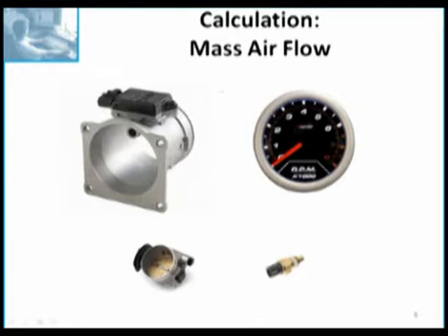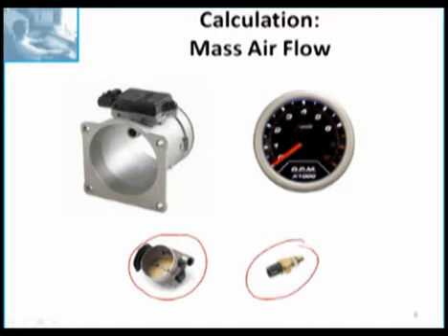The throttle position sensor in a mass airflow car is just a transitional sensor. It says, hey, the throttle is increasing or decreasing or idle or wide open. The other thing I want to mention is that the coolant temperature, a lot of people think it has a big effect on newer cars when it's at operating temperature, but that is certainly not the case. As soon as the PCM has seen that the engine's gone through a warm-up cycle, it pretty well ignores the coolant temperature sensor.